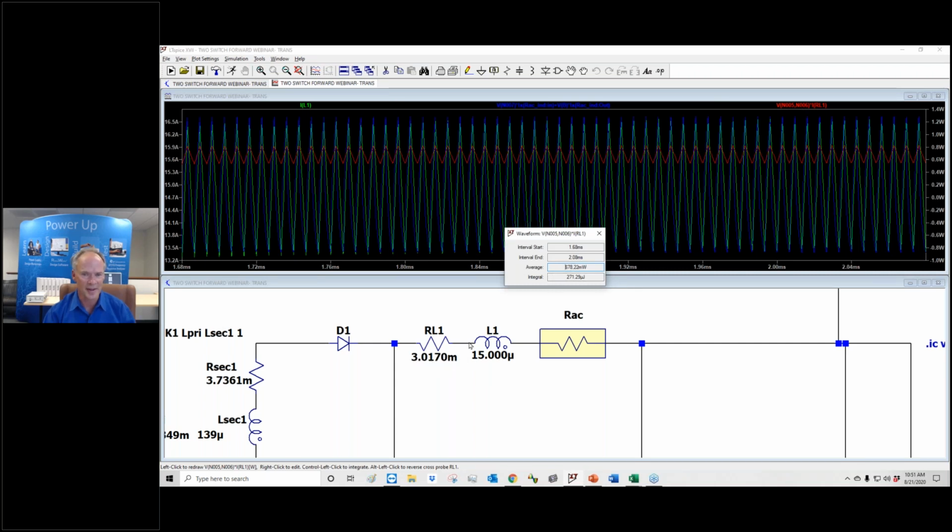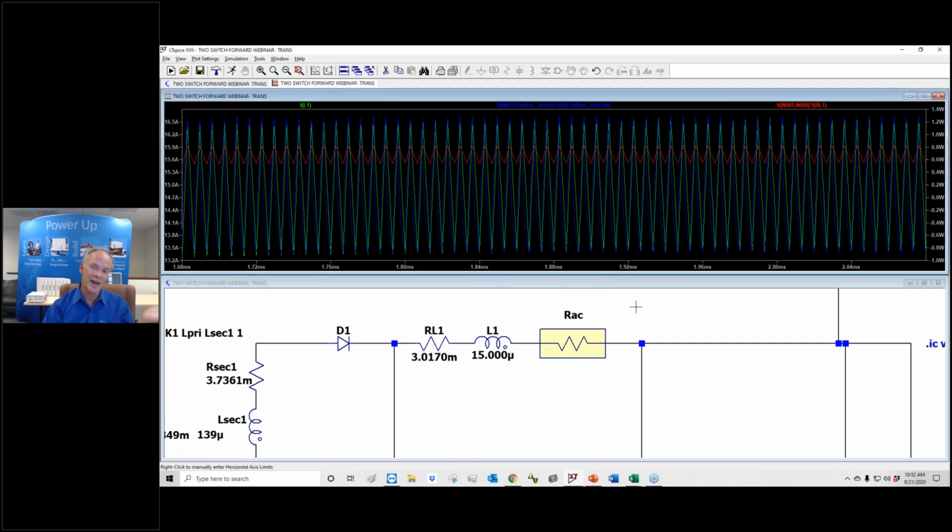This has got resistors gone up. Something happened there in the transfer. I'm not sure what that was. I obviously changed something. But all the losses here are the DC resistor, not the AC resistor. And that's because we're on the output inductor of a buck converter.